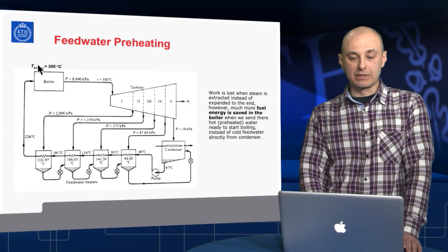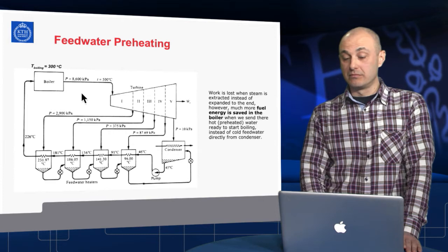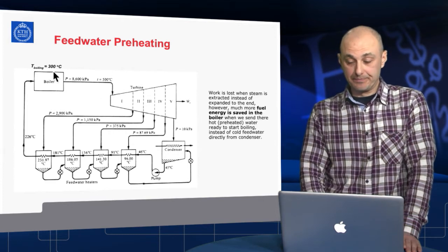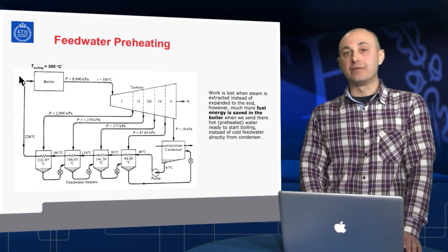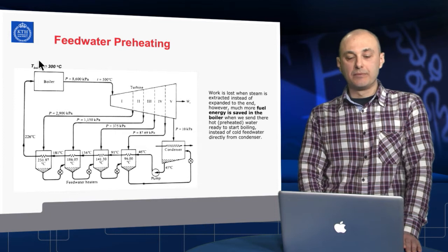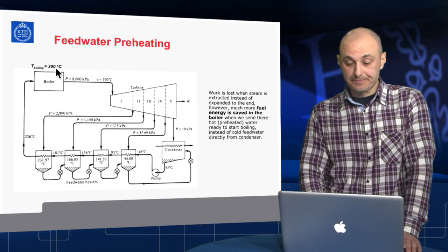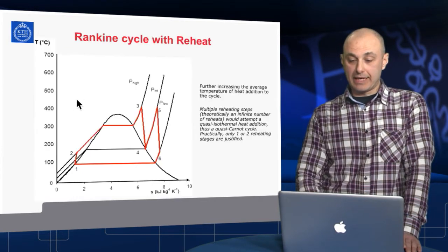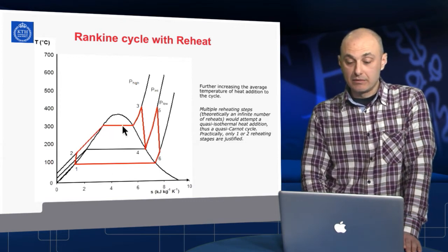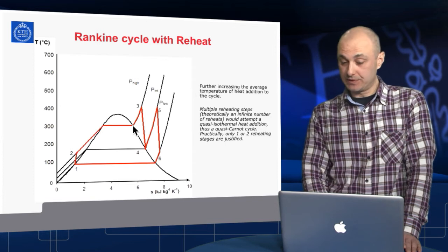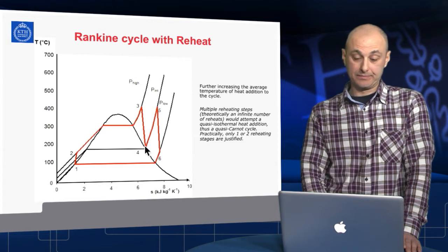We can easily guess what the boiling temperature is when we know the pressure and the temperature of the outgoing steam. The boiling temperature would define the major amount of heat or energy that the water needs to get in the boiler in order to be converted into vapor. Going back to this type of diagram, we can see that boiling water at higher pressures actually takes less heat than if we boil it at lower pressures.